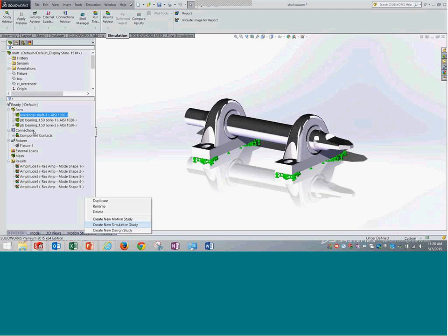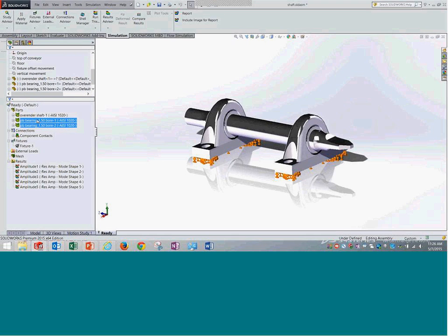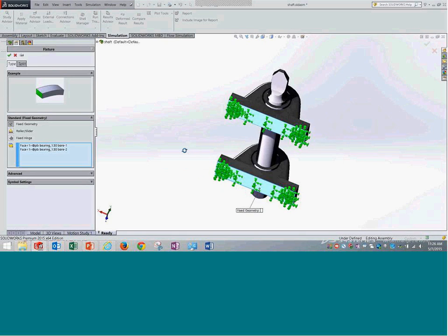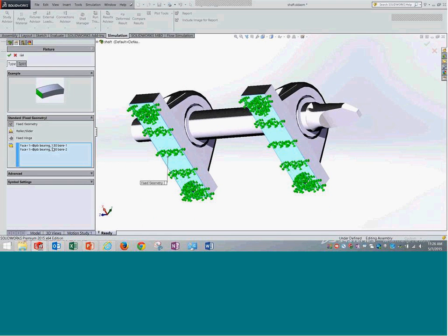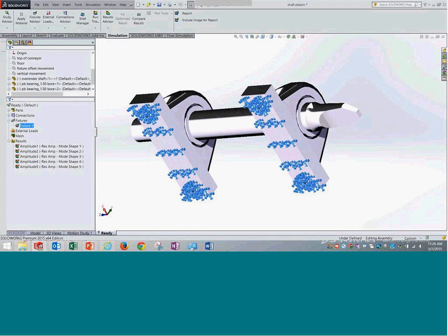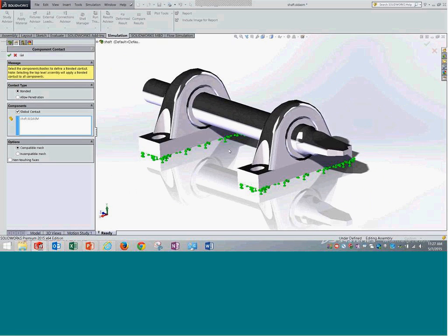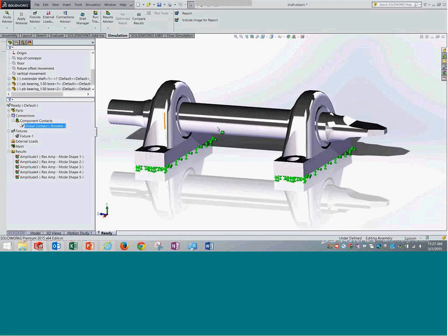Typically, when you create a new setup, you should see this option of frequency. You are going to select that particular option. And material as well, as I told you, different parts with different materials can be given. Then there is the fixture. For the bearings, you can see here at the bottom, these two bearings have been selected at the bottommost surfaces. The connection between the shaft and the bearing can be no penetration. It is free to rotate, but in this case, we are assuming that it is bonded. It is connected.